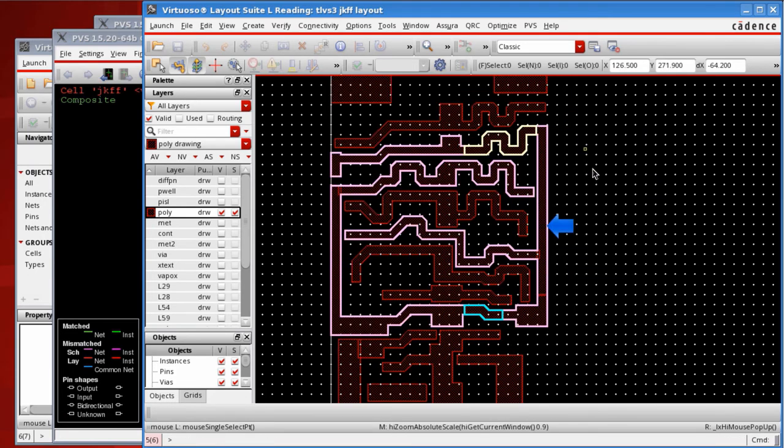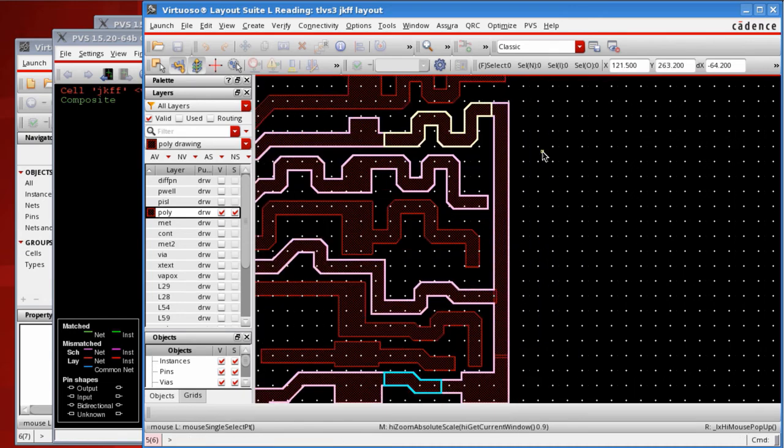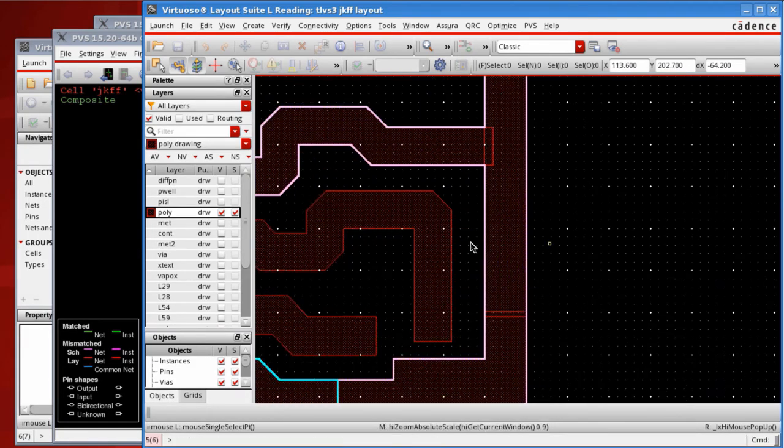Now it's clear that the short is happening somewhere on this track, and we can fairly assume that the short is happening on the right side of these devices. Now you need to manually track it down. We have successfully reduced the possible area where the short could happen. And once you track it down, you could see that there is something fishy out here. Let's try to disconnect here and see if the short is cleared.